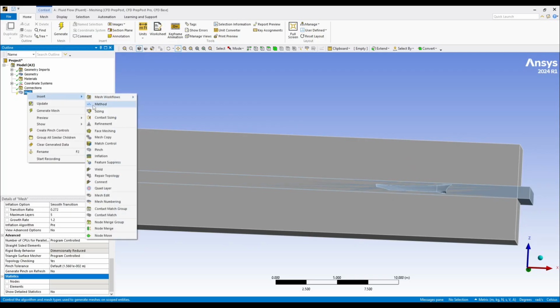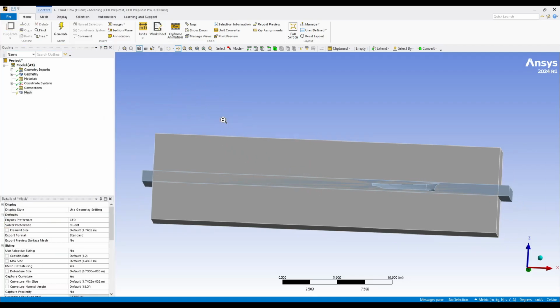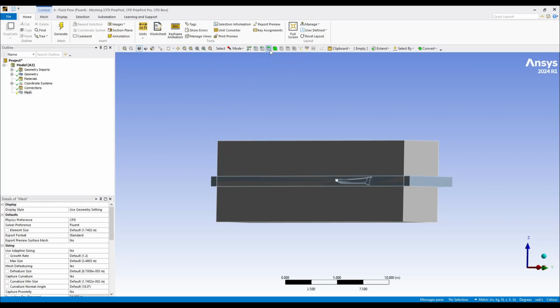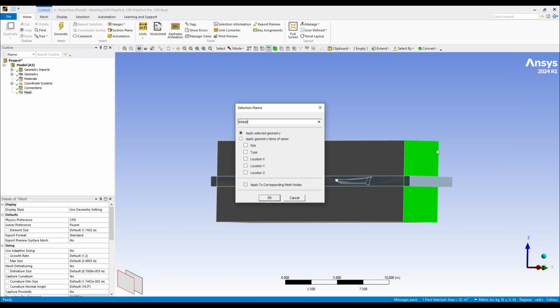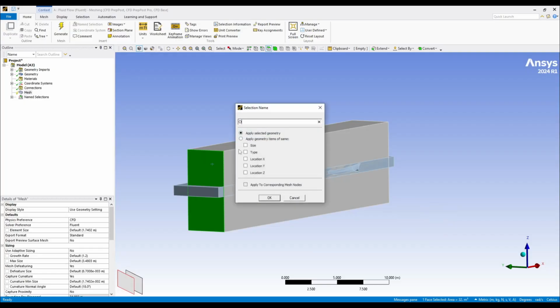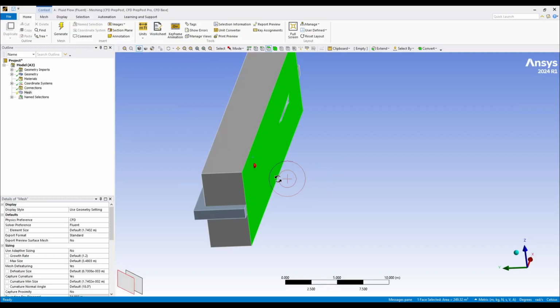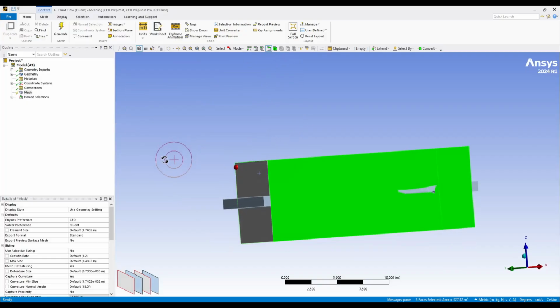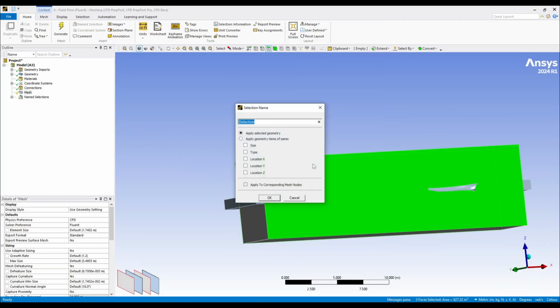We will just here insert add sizing. Now let us first do the naming of the inlet and outlet. That's the most crucial part. We'll just select here and create named section. We'll just say inlet. Then the next segment we select and create, this is outlet. This is the most important part, and we press Ctrl and select the 3 segments and create the named section as symmetry.